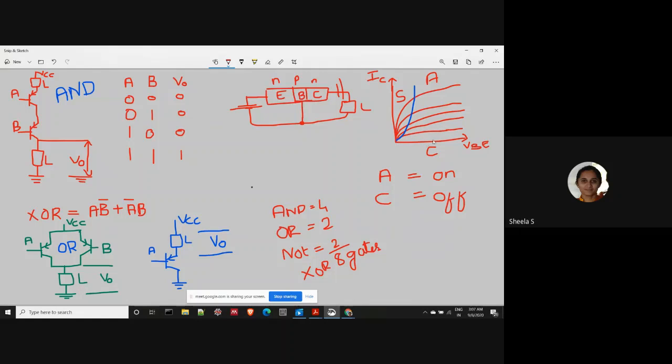If the voltage between base and emitter is less, then the device will be in turned off condition. So as a result, here we will be having the cutoff region. When the base current increases, the corresponding collector current will also increase. So as a result, the current will be rising from minimum to maximum.